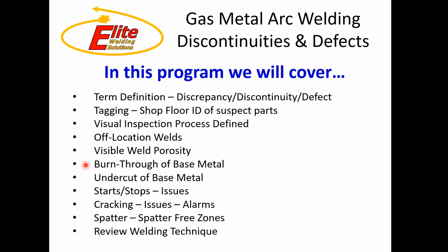Burn through of base metals is going to be discussed. That is when there's a big hole and we have to do something about it. Undercut of base metal: we'll talk about that in some fair detail, because many consider it, in a dynamically loaded structure, that is a structure that's constantly moving, to be a very serious defect. Then stops and starts, cracking, spatter, and a little bit of a technique review. So, if we can just carry on from here, it all sounds good.